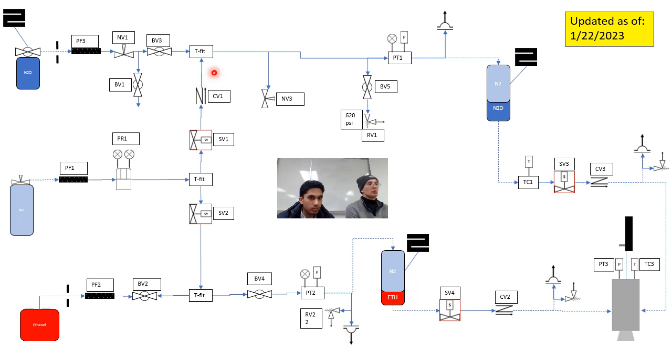And we reduce PR1, pressure regulator 1. So we set it and reduce it to 625 psi, or maybe like 620, 615. I think right now I'm leaning personally toward 615, just under the pressure relief valve. There might be some logical reasons why we need to change that, but it will be in the range of about 600 to 620 psi.